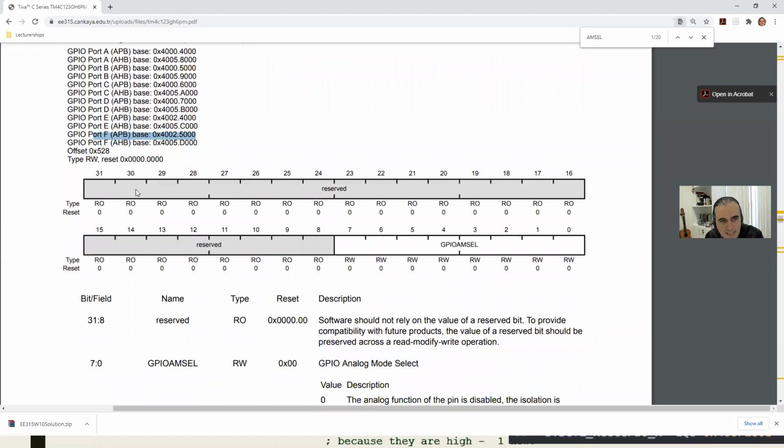So guys, again, it's a 32-bit register, just like R0, but in some other place, a physical register. It's on the digital pad. The most significant 24 bits are reserved. You don't use them. You have 8 bits, for 8 pins separately. You can select analog mode on and off for each pin separately.